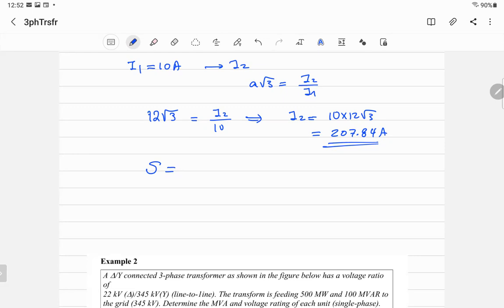Yes. So can't you just find it like you would in single phase and multiply it by square root 3? You can, but why? You already have V2 and I2 and all line quantities. So can you just do it like the regular way with the three phase? Oh yes, tell me about the regular. Well, it's just P plus JQ, right? Yeah, but you don't know P, you don't know Q. You want to get all of it.